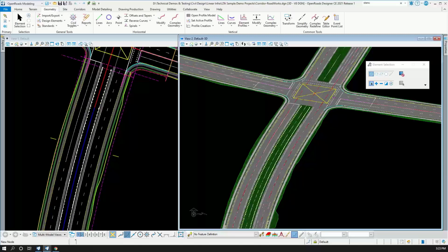Yeah, but of course it depends. When you're creating or utilizing the civil cells, you have to look at the available civil cells in the library if it's applicable to that particular type. But you can create your own. As I mentioned, you can customize it. It just needs some understanding of, again, going back, geometry, template, and corridor, and how it targets your ground. But basically, there's no limit as to what you can create in terms of the type of civil cell.